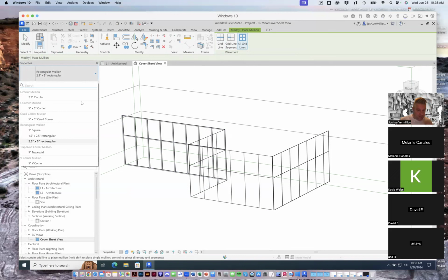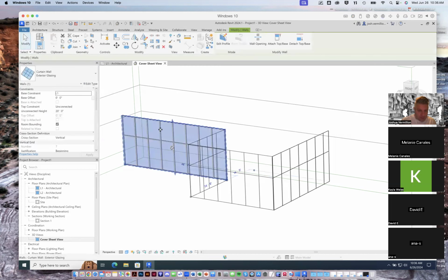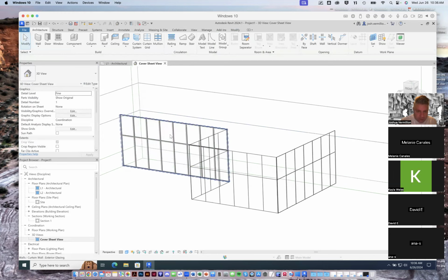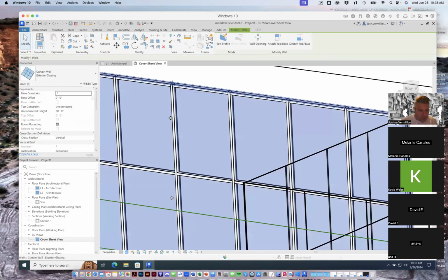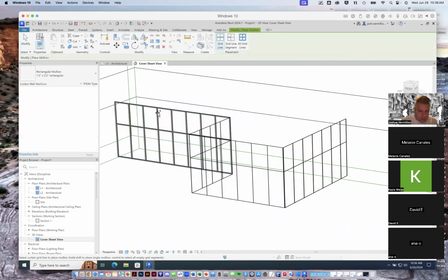That's actually quite beefy. These days, sometimes you don't even need mullions, but you can of course change that and make them a little less intrusive here. Let's see if I can select those mullions now. Come on now. Sorry, I have to go back to mullion. Okay. All grid lines.